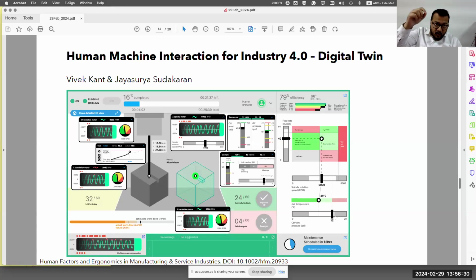Now you have coolant pouring on your tool and the job to keep the temperature down. Otherwise, that will melt and stick to the tool over there. So what we are trying to do over here is visually show that if you increase the feed rate, and if you increase the spindle rotation, it may go into these areas. It also may go into these areas, right? And in this area, your tool will break. So visually, you are ensuring that the constraints of activity in the real world are acting back.